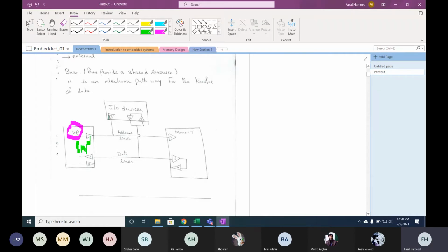There are three terminals. How many terminals are visible here? 3 terminals, right? Yes, sir. And now we also have this enable. Here it will be enable 4. If you look at tri-state buffer 4, can you see it? Yes, sir. Actually this tri-state buffer 4 is the output to the memory. Okay? It will also have an enable.